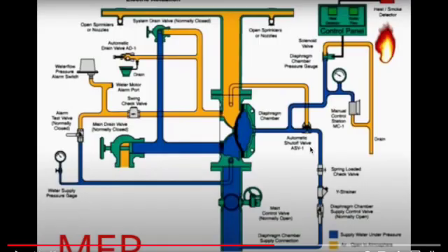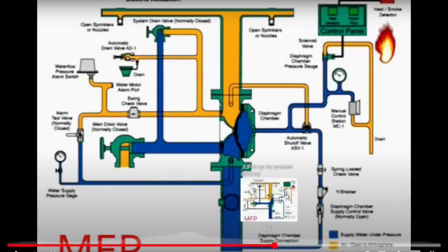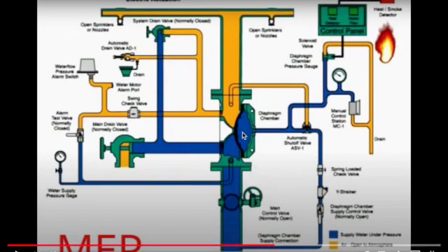So this is a typical form of a deluge system. In this, here is our main deluge valve, which is being pressurized by water, and one inlet of this line pressurizes the diaphragm valve closed. When this smoke detector detects fire, it sends a signal to this solenoid valve, and this solenoid valve opens. When the solenoid valve opens, the system becomes depressurized, the diaphragm of the deluge valve opens, and the water comes out of this system to its open sprinklers. So this is how it works.